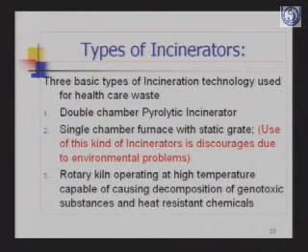What are the types of incinerators? There are three basic types of incineration technology used in healthcare waste. First is the double chamber pyrolytic incinerator. Second is the single chamber furnace with static grate. Use of this kind of incinerator is discouraged due to environmental problems. And third is the rotary kiln operating at high temperature, capable of causing decomposition of genotoxic substances and heat resistant chemicals.